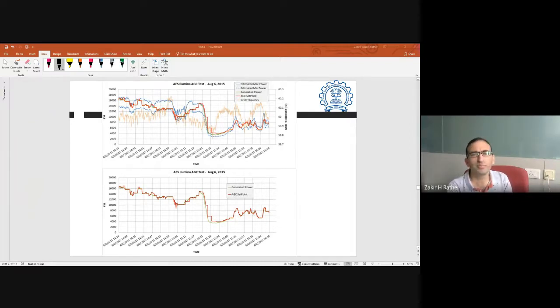See, inertia, we have been talking about inertia from the generation side only. But there is a potential inertial support from the load side also. And this comes from particularly rotating machines, which involve primarily synchronous motors and induction motors as well. So synchronous motors will participate in the inertial support similar to what I explained for the synchronous generator. But induction motors will also support the grid.